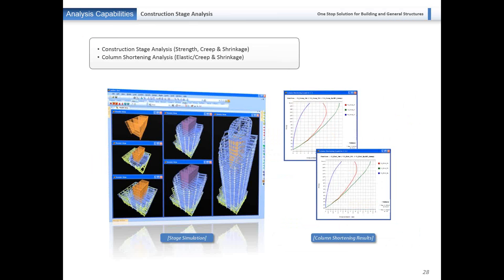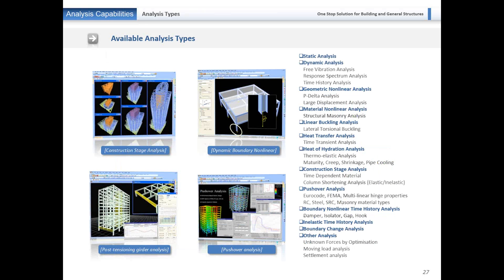So loading, you can add the loading depending upon what you need. We have a good type of options: one way loading, two-way loading, pressure load. For the one way loading, you just define the loading and you can directly apply. You don't need to model the slab, because it's automatically taken care of by the program. And if you model the slab, then also it's fine. You can directly apply the pressure loads. These are the two options we have.